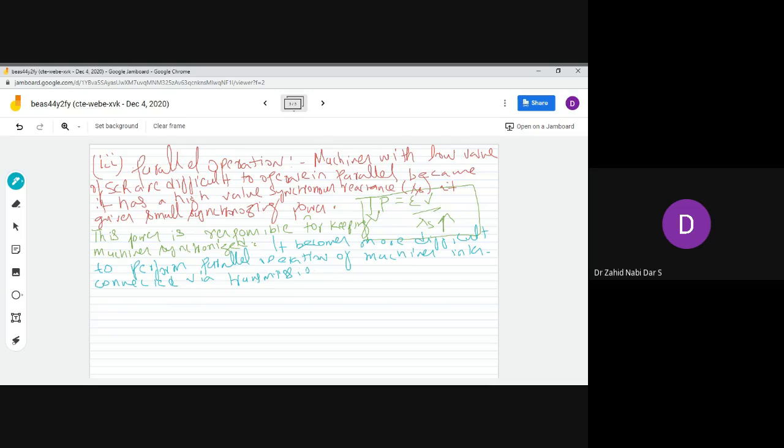This is one concern we have. Why is this so? This is because, if you notice, the impedance of the line between the generators adds directly to the sum of impedance of the machines.